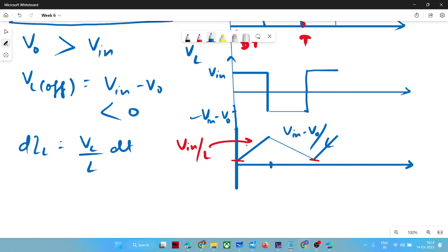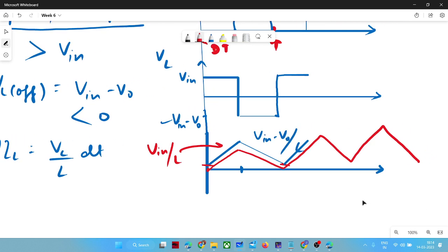And even these slopes, let us suppose that it has zero initial value. It may rise till some value, but it will decay with the same slope, even in the transient condition, right? Because it has to follow the fundamental properties of the inductor, or the KVL and KCL. These rules cannot be violated. So it will decay like that, but slowly it will rise, and at steady state it will pick up its initial and final value.